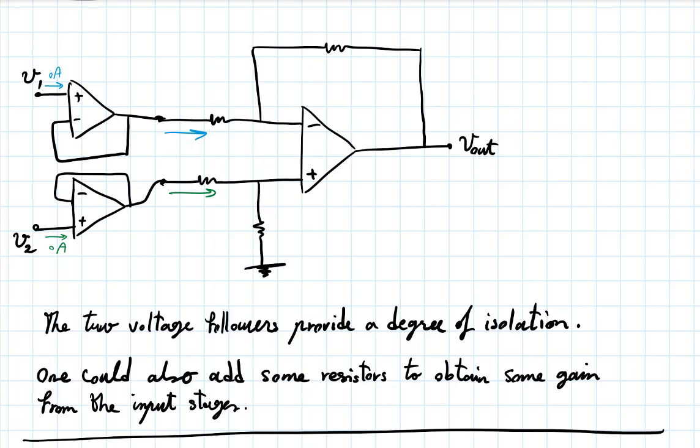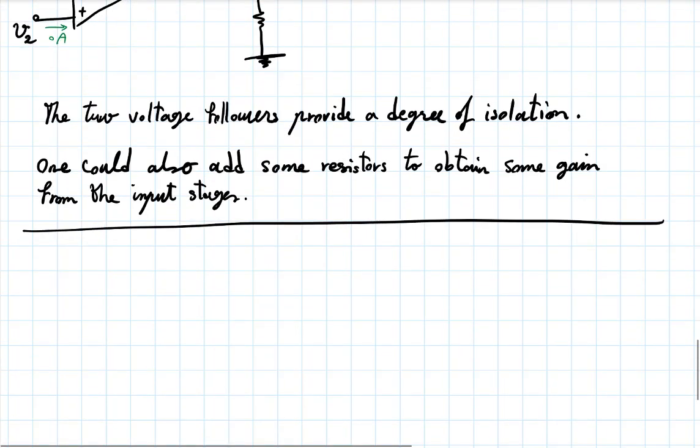But what if you said, instead, I will make an amplifier with a gain of 1,000? Now, maybe a lot more reasonable. I'll have a 10 ohm resistor and a 10 kilo ohm resistor. Give me a gain of 1,000. But then I'll stack 3 of these one after the other. Right? Now I get my gain. So this concept of stacking or cascading op-amp circuit modules to gain new functionalities or improve is very common.